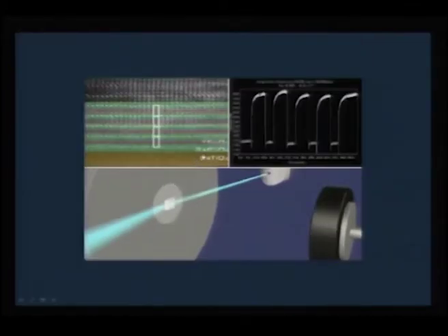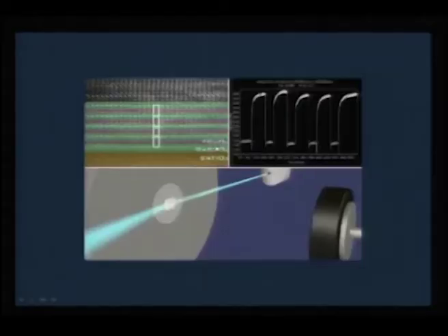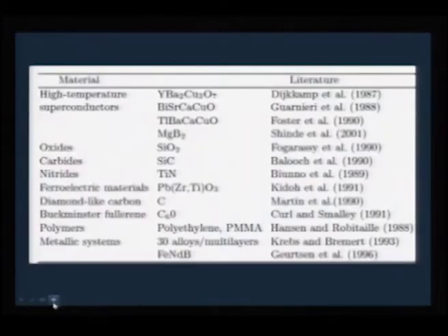In this case, this is your SrTiO3. Then you can put this green patch, which is nothing but your barium cuprate, and then you can put yttrium cuprate and barium cuprate. You are essentially imitating a unit cell, and you can do that by taking a separate target of BaCuO2 and a separate target of YCuO2 and keep on repeating the deposition, and this can be monitored using the RHEED oscillation. Such sophistications are already available in today's commercial PLD instruments.